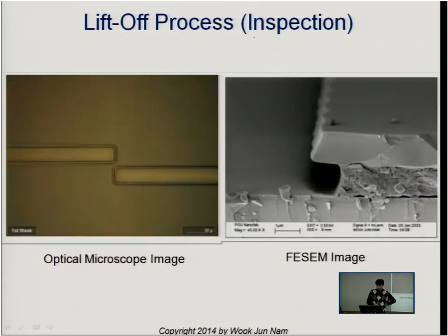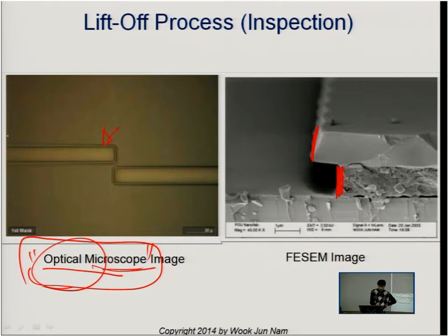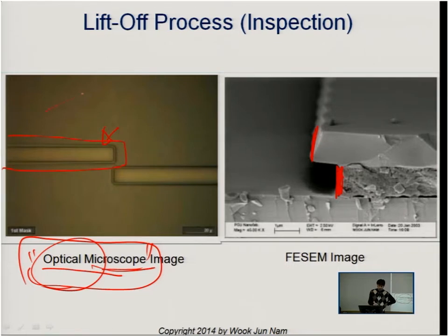When you do the lifter, you will normally see this image from the optical microscope. You will always see these double lines. The inner lines represent this interface, and the outer line is this. Using this optical microscope, if you want to do a little bit more undercut, you should use a red filter, so you do not hurt the photosensitive layer. If you just observe under the red light and do further development, you can keep increasing the undercut. So that's one of the techniques you can use.